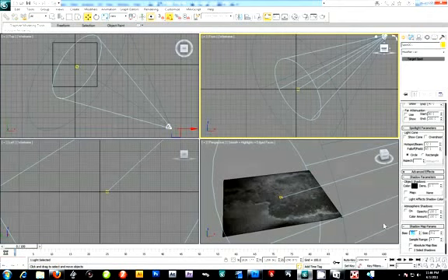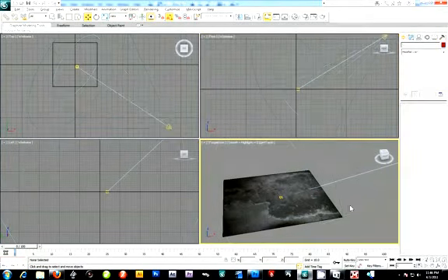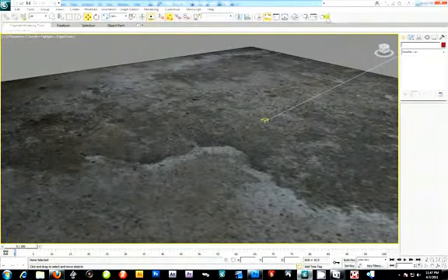You want your shadows to stick to the object. Not that we have anything right now to cast shadows. And I want to probably crank that up to 1024. My sample range is fine at 4. Alright, so I'm going to go to my perspective here. And now with our lights in the scene, I'm going to render this out.